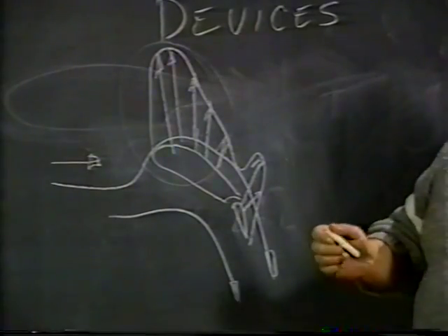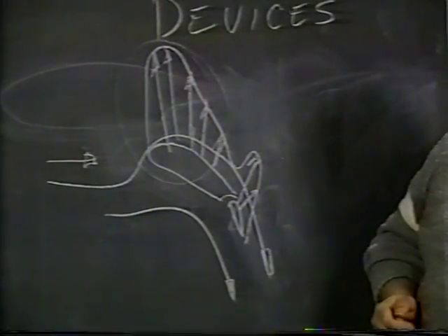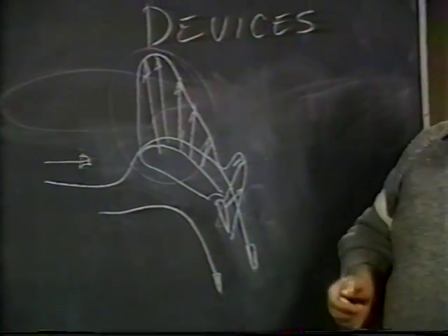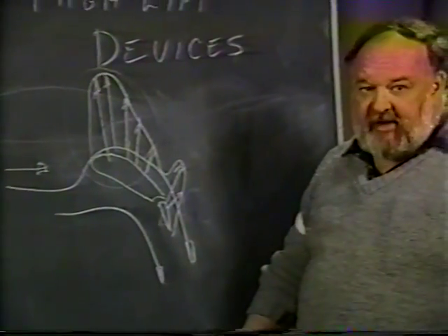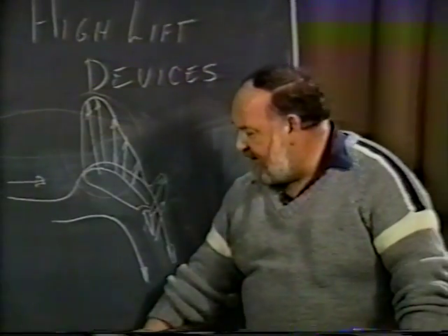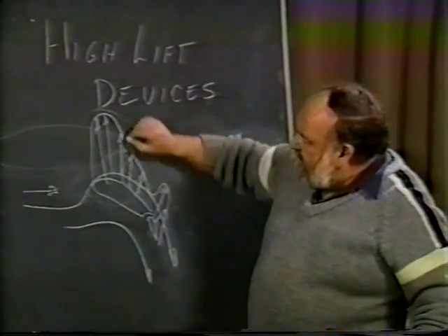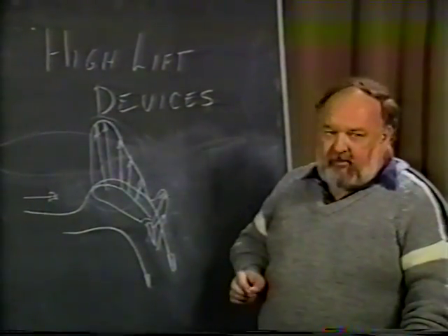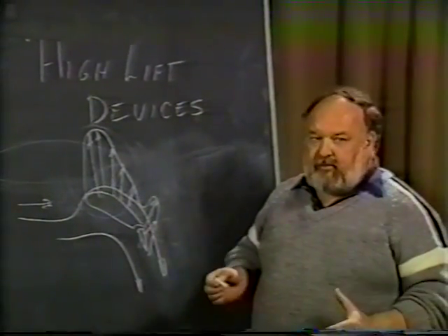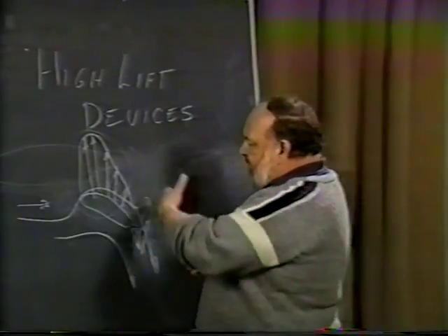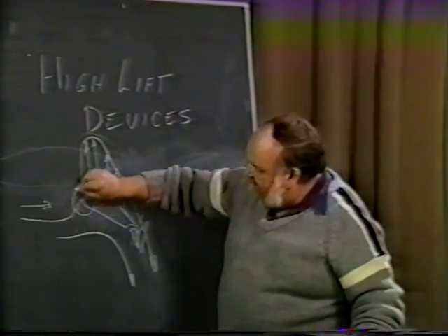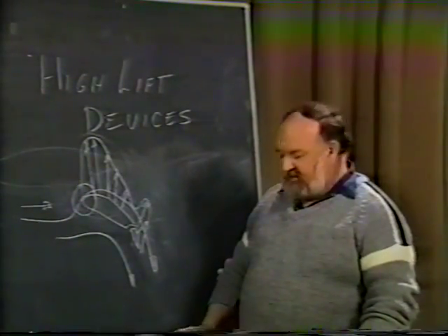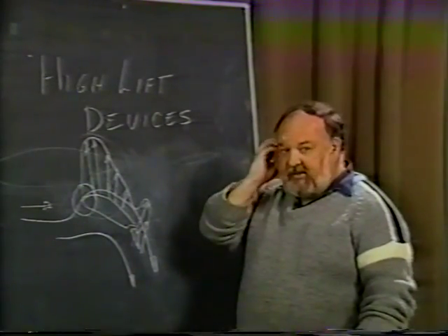I mean, you can go from a lift coefficient of 1.6 unflapped to lift coefficients of 3, almost doubling the total lift. And even higher, in fact, by going into a really proper design. Well, if you're going to increase the forward portion of the wing to lift more, to have the pressure get lower, to have the airflow flowing over better, you have to watch very carefully what's happening to the leading edge itself. So this is where we come into leading edge devices.